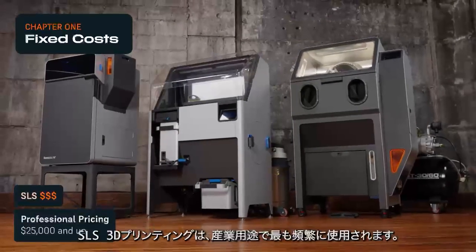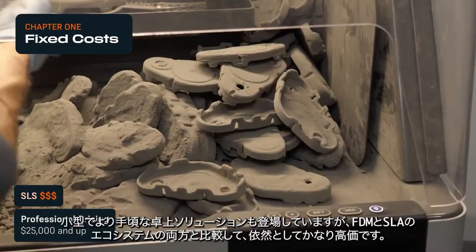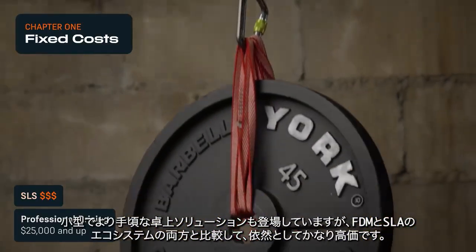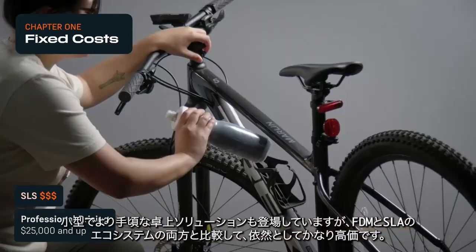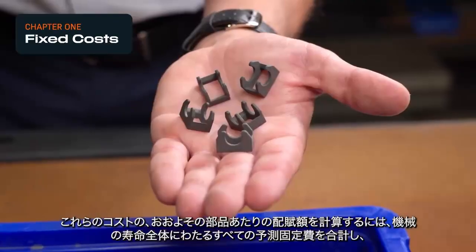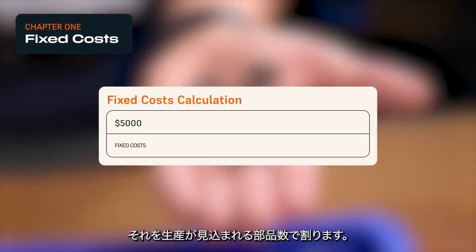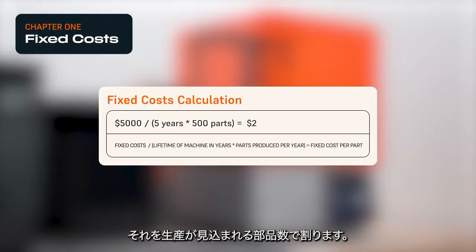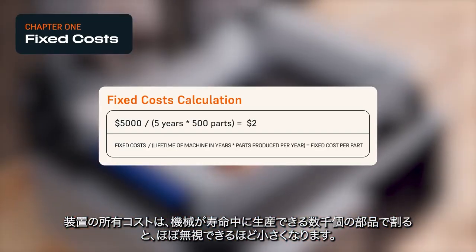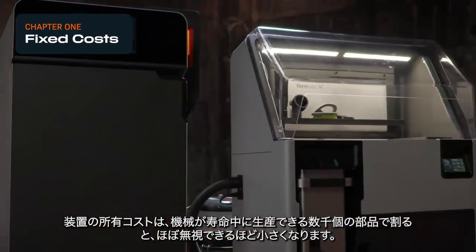SLS 3D printing is most often used in industrial applications. It has become available in smaller, more affordable benchtop solutions, but it's still priced considerably higher than both FDM and SLA ecosystems. Calculate a rough per-part attribution for these costs by adding up all of the forecasted fixed cost over the lifetime of the machine, and then divide it by the number of parts that it is expected to produce. Equipment ownership costs can become almost negligible when you divide it among the thousands of parts a machine can produce over its lifetime.